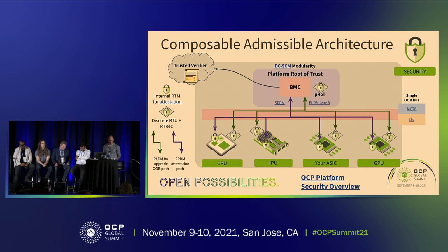The order of measurement really matters, and one of the things Andreas mentioned is that it's not just measuring code. What you're measuring is the device's state, and it can maintain that state post-measurement. So it has the right integrity to maintain policy. It can maintain the attested state even across a reset. If it's reset, it's coming back to the same state. So you're measuring not just code, but configuration, also security properties, and so on. Okay.